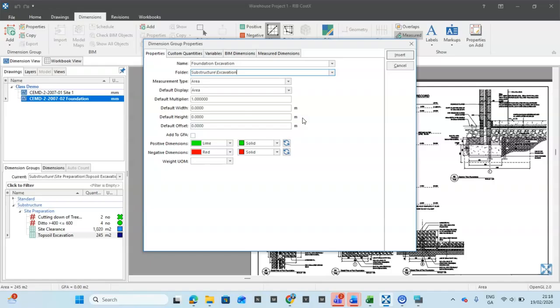Because we're going to be measuring excavation, if you go to your grid rules of measurement, excavations are measured in cubic meters except topsoil excavation, in which you have to state the average depth of your excavation in the description.